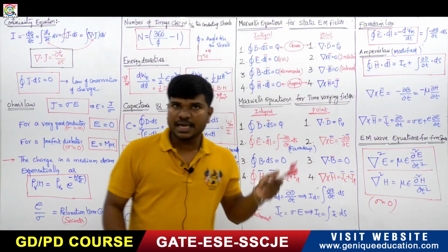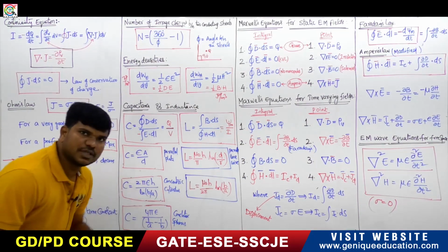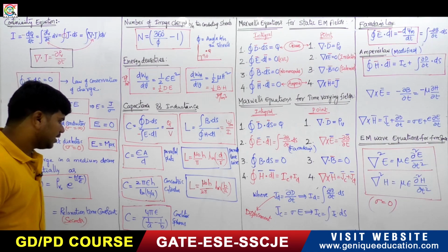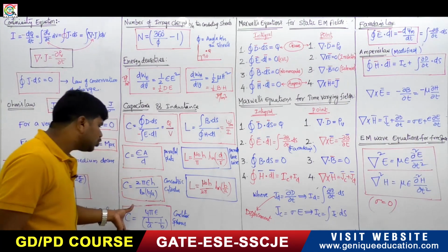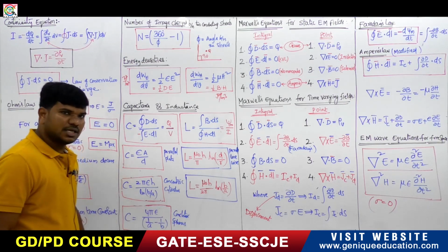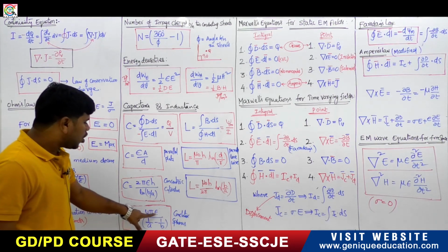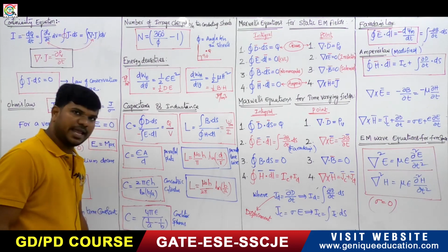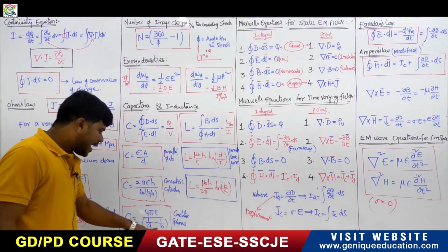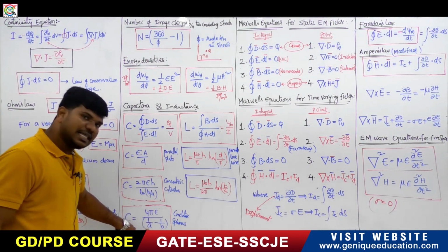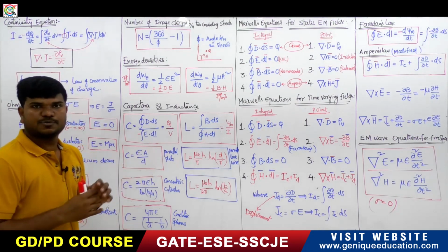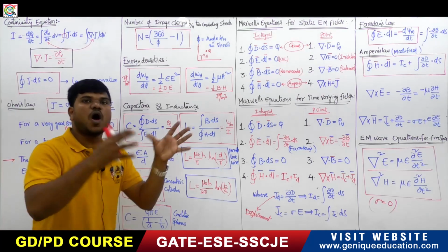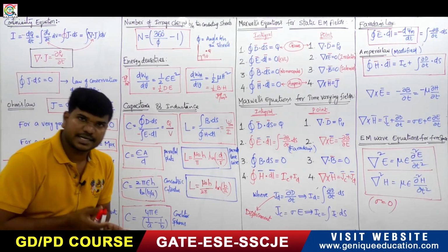Okay, here h represents the height of the concentric cylinder, right? So if you come to the concentric spheres, it is equivalent to 4 pi epsilon divided by (1/a minus 1/b). Again, a is representing the inner sphere radius, b is representing the outer sphere radius, right?